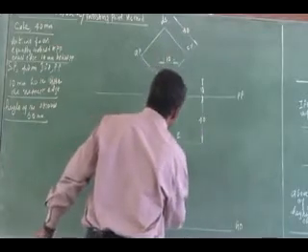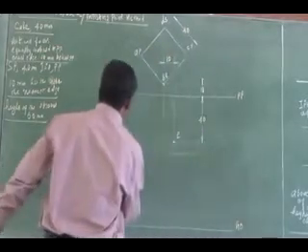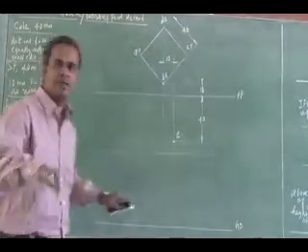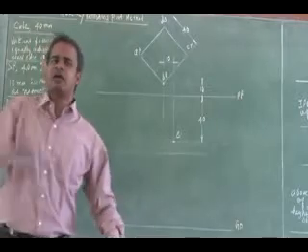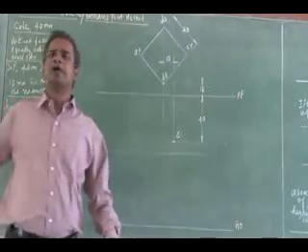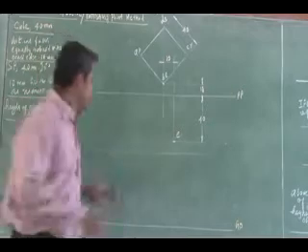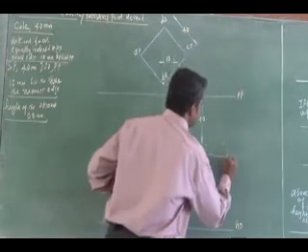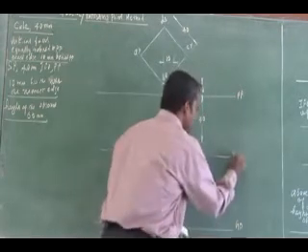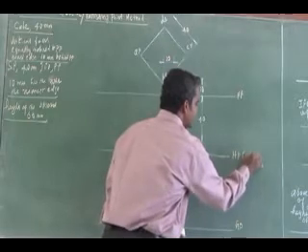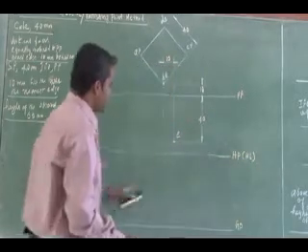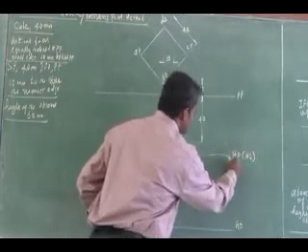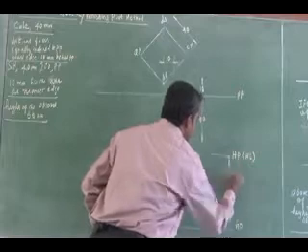Now on this 60 mm, what am I going to draw? See here carefully. From the height of the observer, in the previous method, which plane did we have? The horizon plane. So in two dimensions, the horizon plane I can show as HL, the horizon line. Altogether it is the horizon line. So what is the height of this line? It is 60.